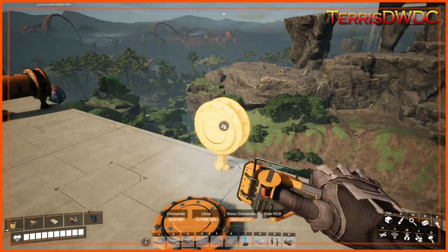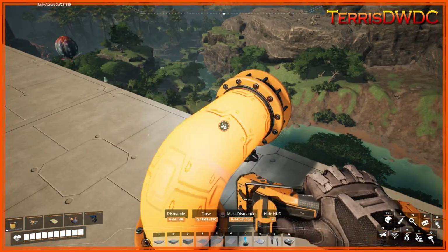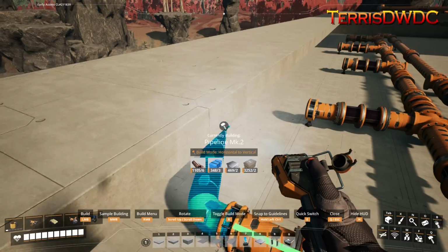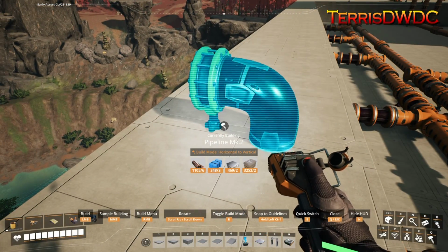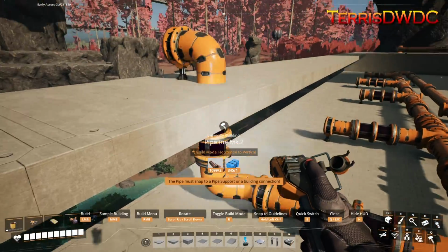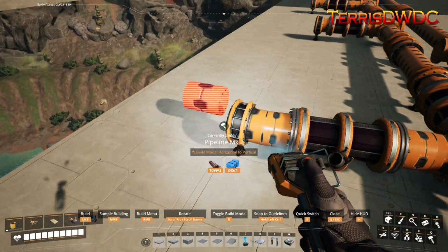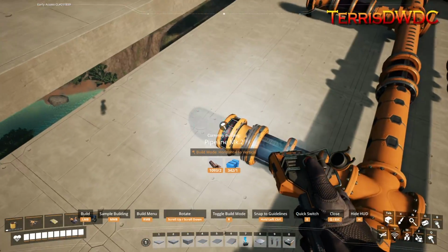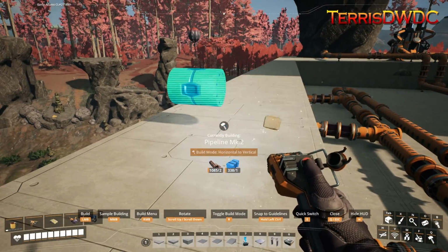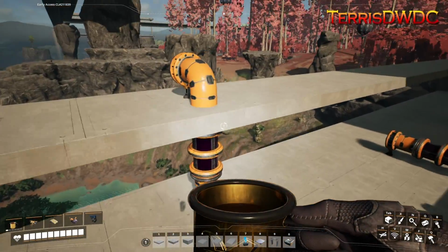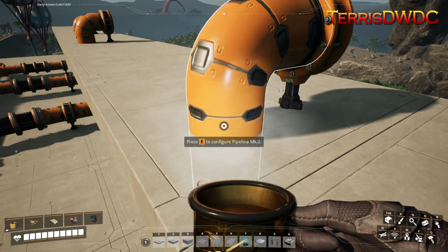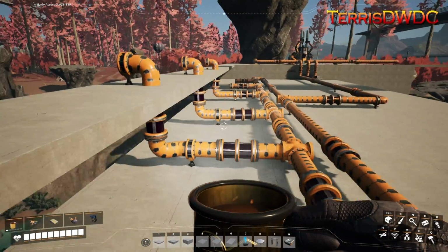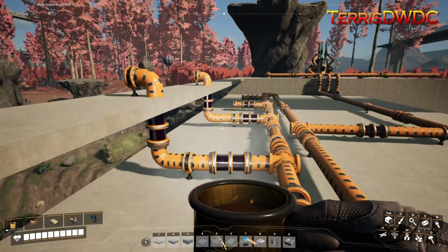So what do you do to get around that? This would be the only acceptable clipping that you could go through: bring it up so that you're at your 90 degree up, your 90 degree out, and use that as an acceptable clipping for this. And your life is going to be so much easier, because now it's just a continuous piece of pipe. There isn't a joint here where something could go wrong with the fluid transporting beyond it. And you're going to be so much happier with how you deal with that.